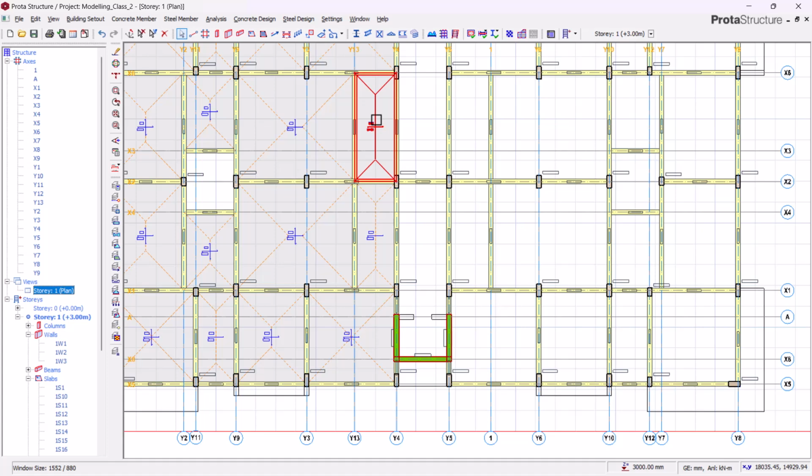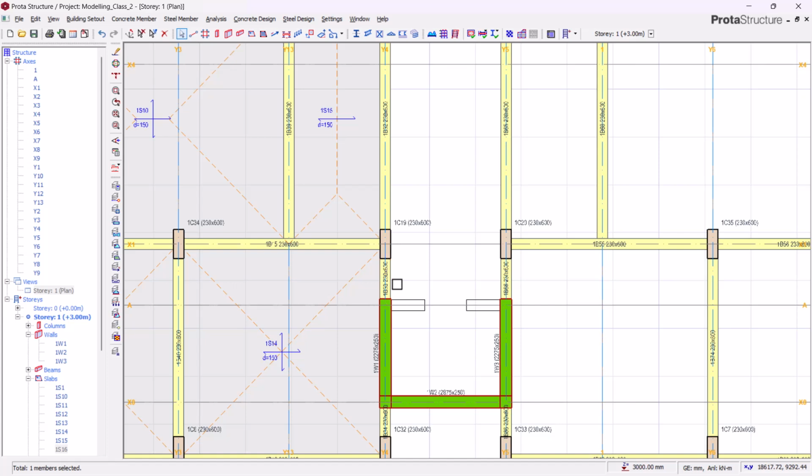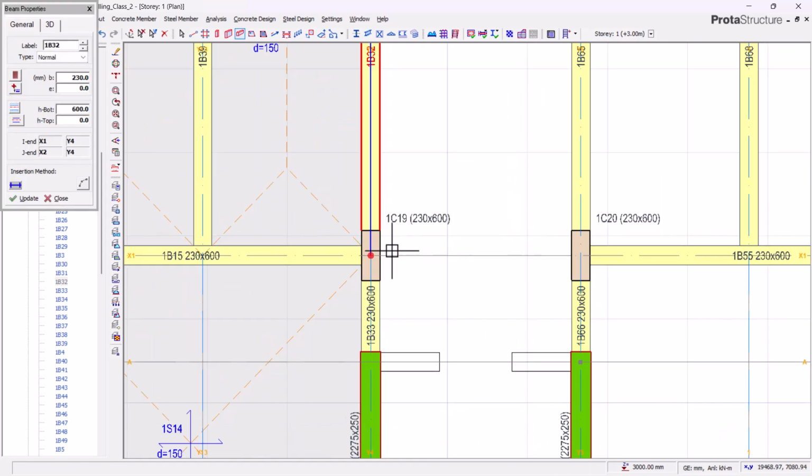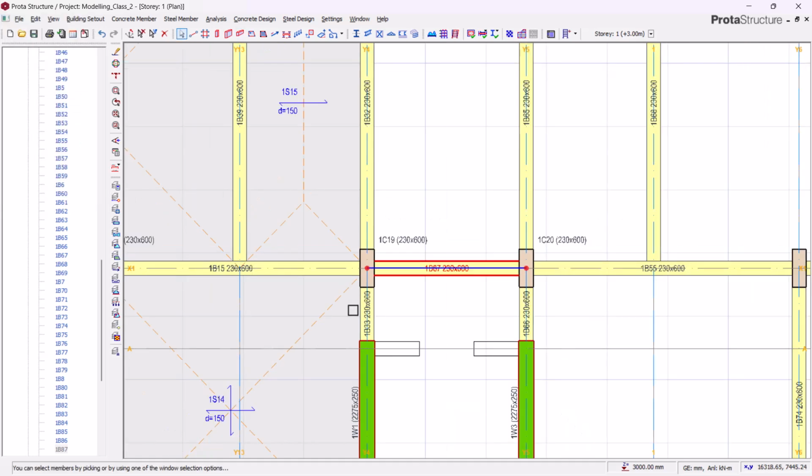To model this, I'll click here, and one more thing, let's insert a beam over here. Okay, so this part will act as a panel, right? So this other part can be considered when they are inserting the shear wall. So we'll come to this, we'll right click, properties, and we insert a beam right over here. So we'll close this up and close.